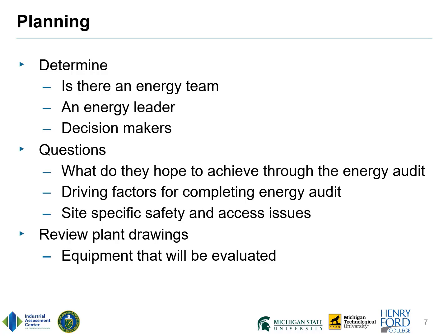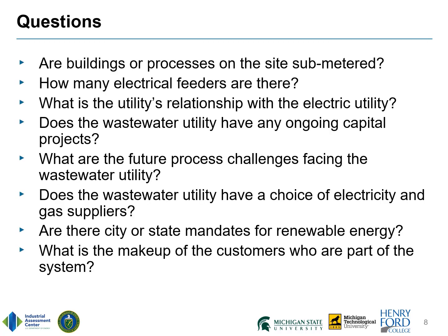Before scheduling the first site visit, discuss with the client what they hope to achieve through the energy audit, the time frame, expectations, the driving factors of why they are completing an energy audit, and any site-specific safety and access issues. Lastly, review the drawings to ascertain what equipment is located at the plant and generate a list of equipment that will be evaluated during the visit. Make sure to ask lots of questions during the site visit.